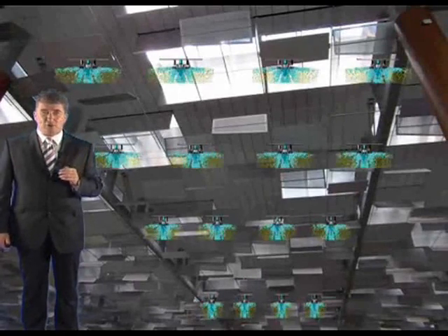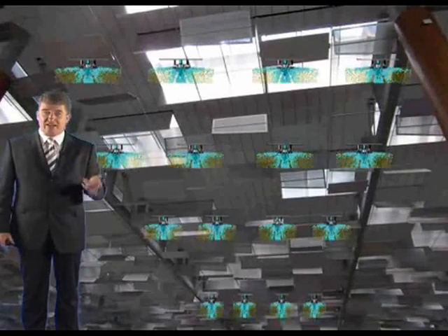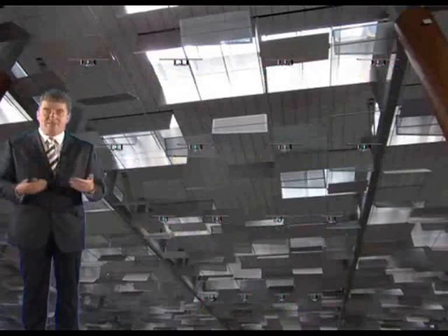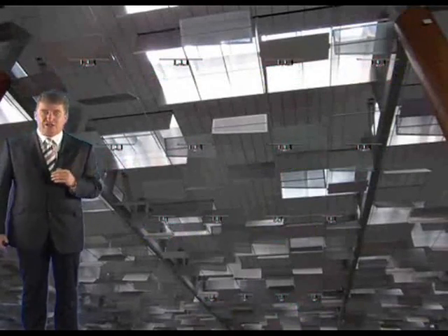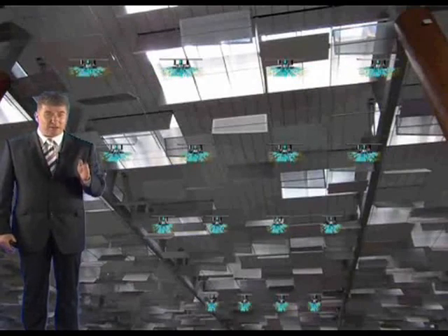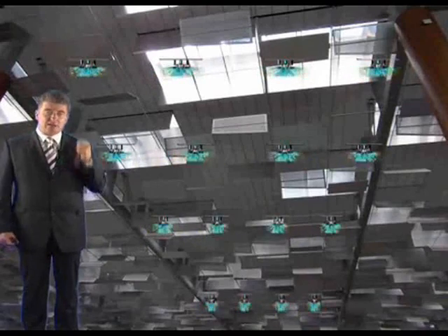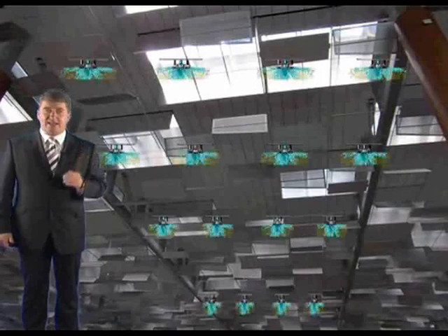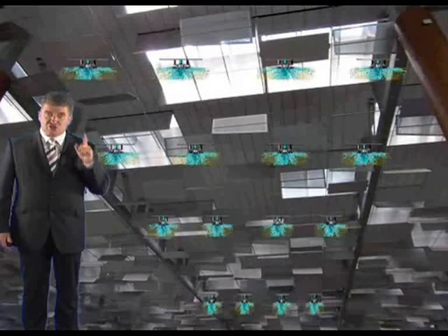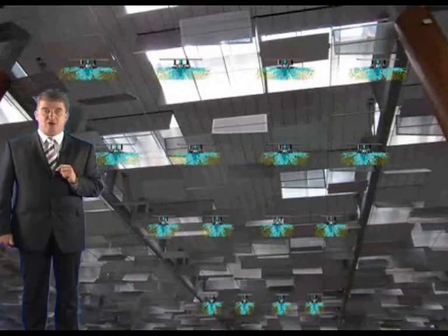The provision of smoke vents reduces the spread of fire products throughout the building due to the release of hot gases, getting it all out, and fire material from the building. This will improve the visibility and conditions in the building for occupants to be able to escape and for firefighters to undertake firefighting operations. So these ventilation systems are excellent. And generally, it is accepted that early vent operation does not have a negative effect on sprinkler performance.